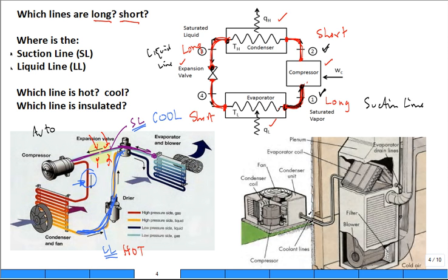And actually, if you bring the cool refrigerant into the compressor, it keeps the compressor from getting so hot. So it's better to feed it saturated vapor, not superheated vapor, relatively cool saturated vapor. It's good for the compressor to feed it saturated vapor, not liquid. Don't feed the compressor liquid. It'll break. But you don't want it to be superheated vapor. It actually provides cooling to that compressor.